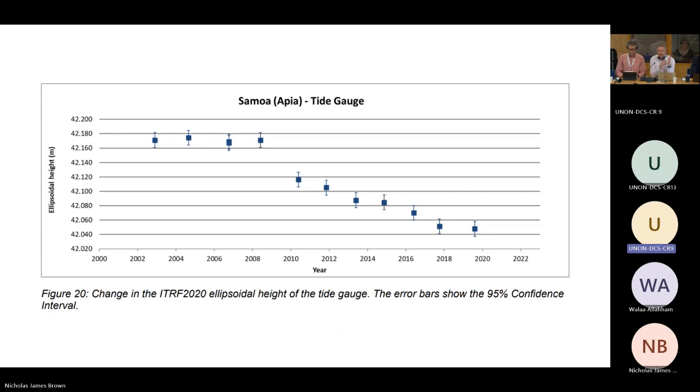They have a tide gauge with a GPS mounted on top, and then you can do everything in one location. The reason that wasn't done for this particular study is because we felt that a GNSS site on the land, embedded into bedrock or very strong rock, was going to give us a more accurate and reliable result.